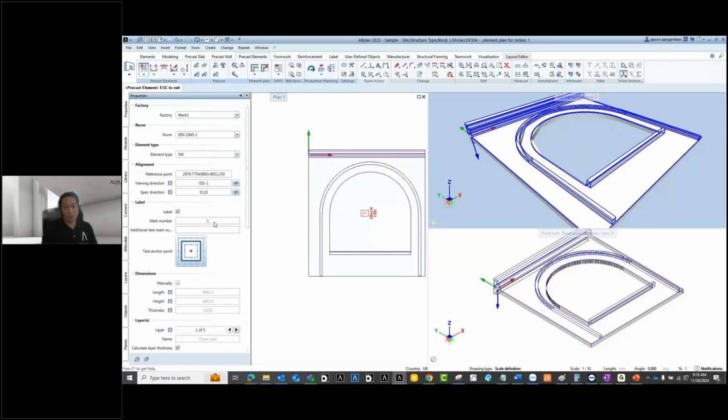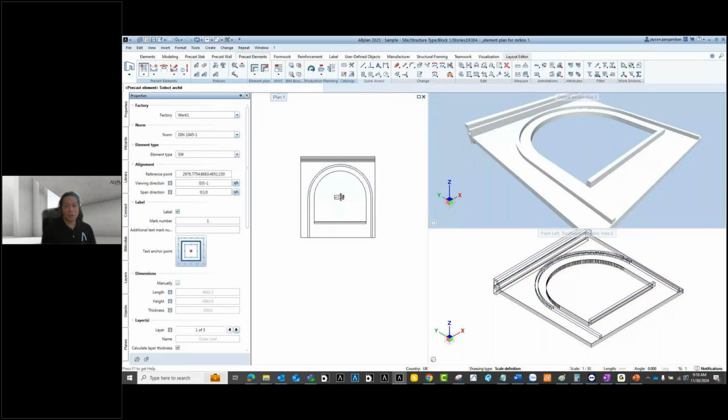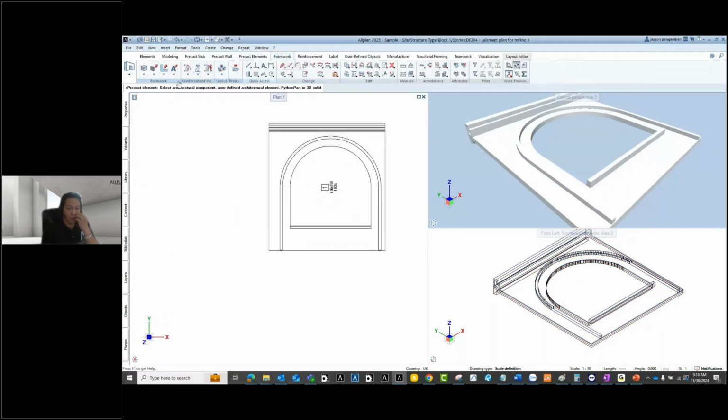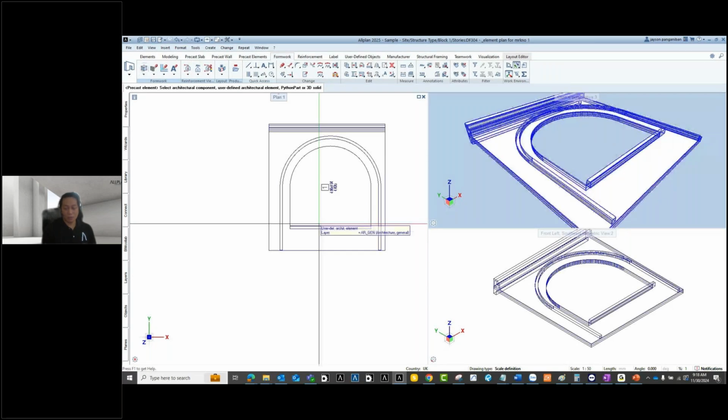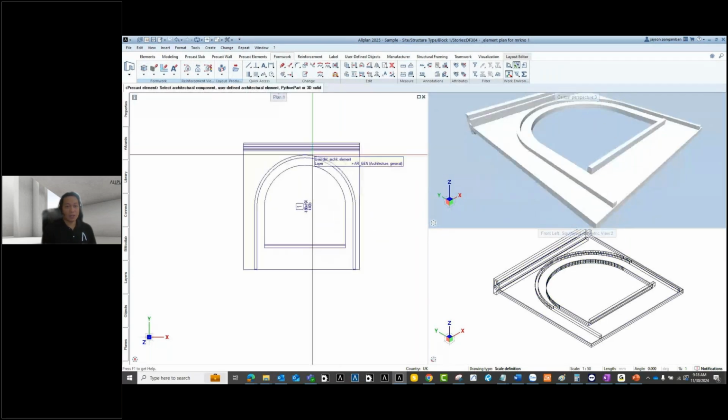So for the precast elements, we just need to create a formwork. So we just go to this formwork tab. In the formwork tab, you have these functionalities, so everything is available here. And then we just have to say create a formwork area. The first step is actually to create the formwork areas, so I will just select my element.